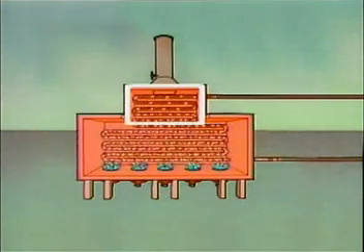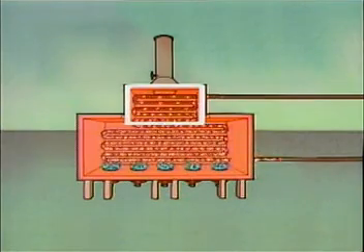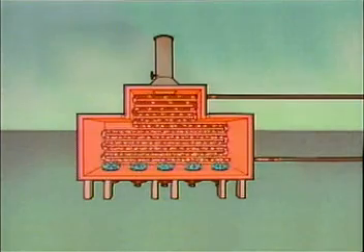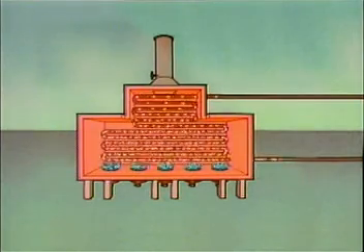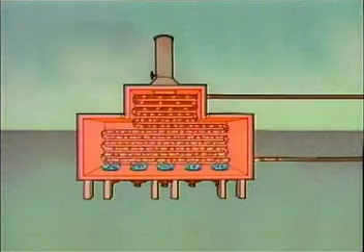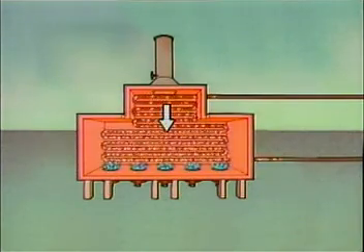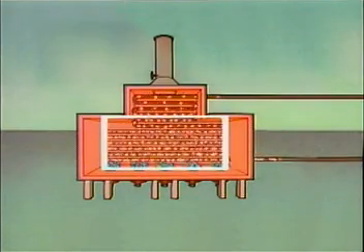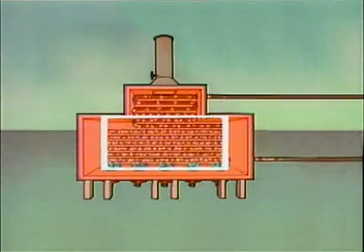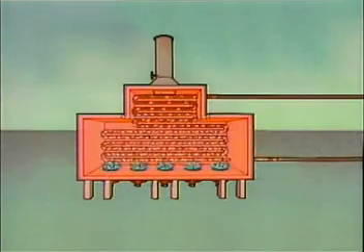This arrangement allows the fluid to be preheated by the combustion gases before it reaches the radiant section of the furnace. Preheating the process fluid makes it possible to bring it up to the desired temperature while burning less fuel. In other words, it makes the furnace more efficient. From the convection section, the process fluid passes through the tubes in the radiant section. The process fluid becomes hottest in the radiant section because more heat and higher temperatures are available.